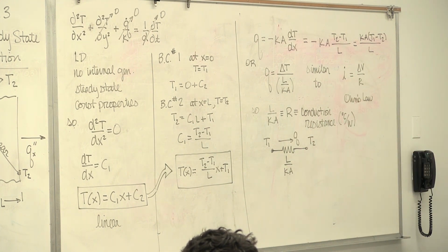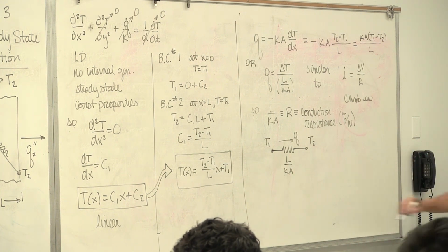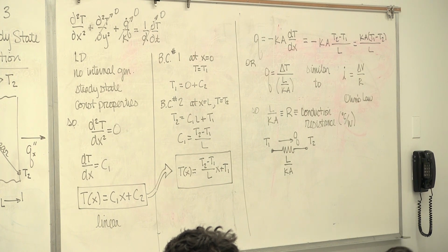So we can model a plane wall as a thermal resistance. I can model this concrete wall as a resistance. How thick is the wall? I don't know, 6 or 8 inches thick from here to the hall. What's K? Go to the back of the book under concrete. What's the area? Forget the door. It's the height times the length.